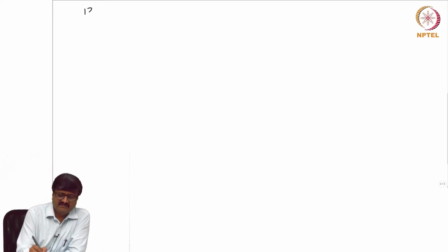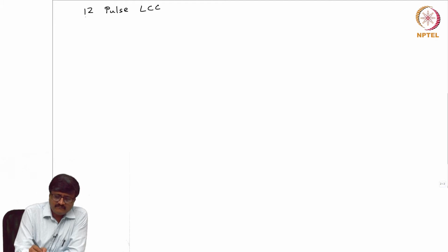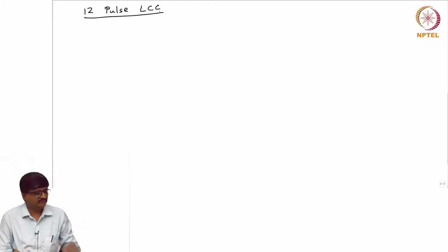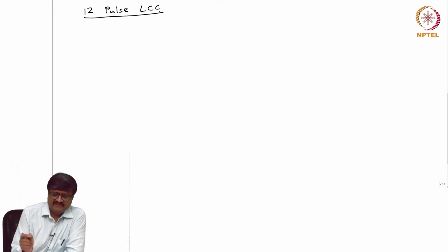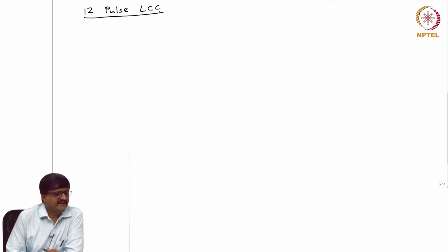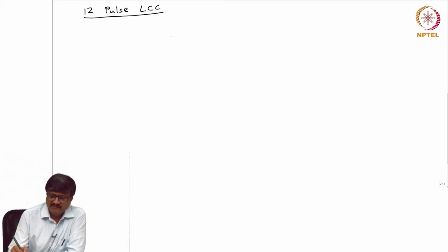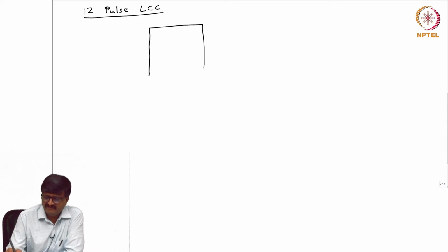Let us continue our discussion on 12 pulse LCC. Now, we have seen the circuit. I will not try to draw the entire circuit diagram, but I will just show that there are two 6 pulse LCCs in addition to two transformers.